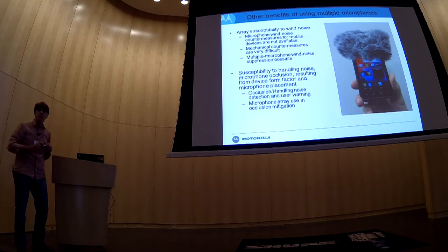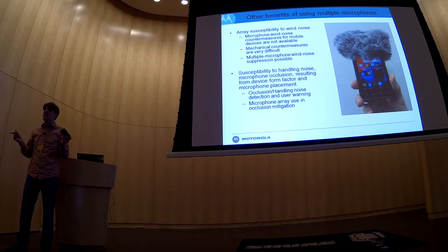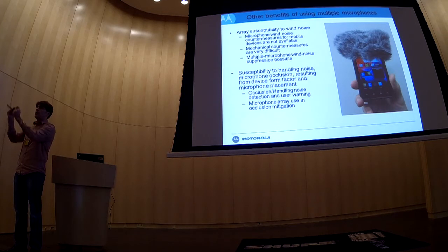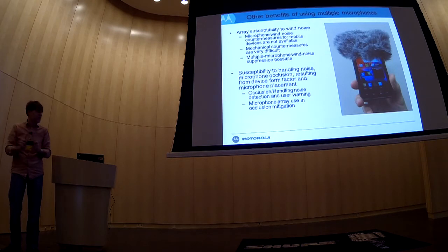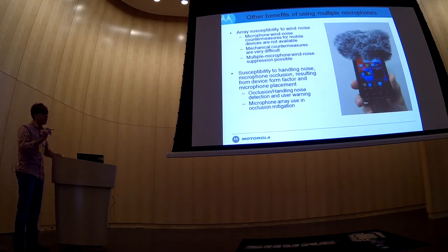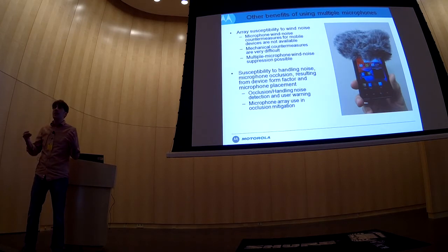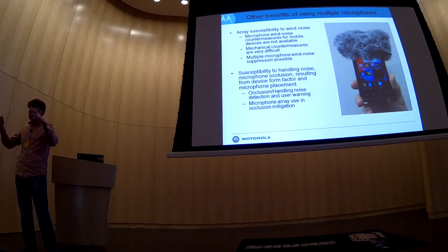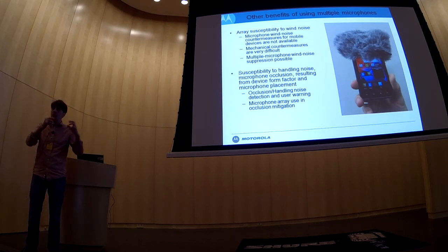So it so happens that placing the microphones where you want them makes them very easy to occlude, because the user will do this. When they do that, well, guess what? They just put their hands on the microphones, at least one of them. Now, one very nice feature about the microphone array is that there's an implicit built-in diversity and robustness in it, so that if we occlude only one of the mics, that will not destroy the audio, in the sense you will still have audio in the video recording.